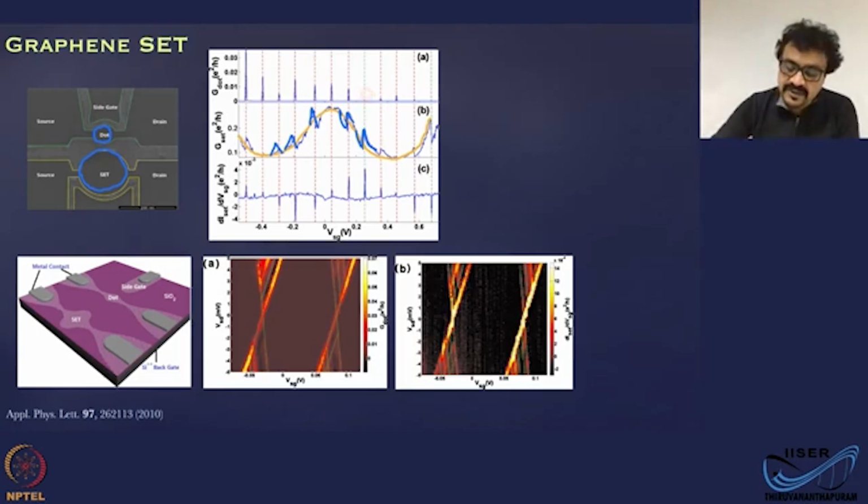And as I mentioned, there are many places where you don't see conductance oscillation, because those are not detectable or current levels are very low, you can see here, but this SET is going to capture almost all of those things. Here, what you have is a Coulomb diamond plot taken from the direct current or direct transport measurement from the graphene quantum dot. And this is basically the same plot where you have recorded the changes in the SET conductance. And you can see that whatever features you see here, you can extract all those features with a higher level of clarity when you use a charge sensor.